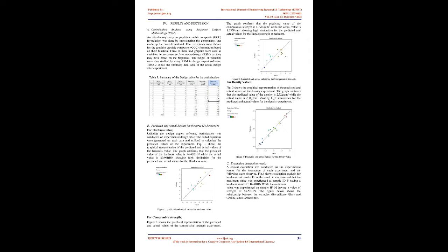These components represent a total of 58 weight percent of the total formulation, that is, A plus B plus C equals 58%. Other materials, held constant, will make up the difference, 42 weight percent of the graphite crucible composite. These include 30 weight percent graphite and 12 weight percent silicon carbide, SiC. For purposes of this experiment, they are ignored. This experiment was conducted with the Design Expert software 11.0.